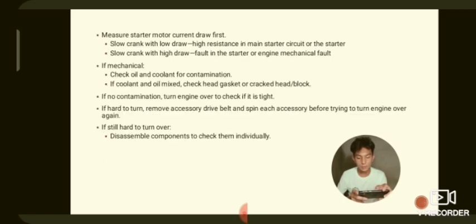Measure the starter motor current draw first. Slow crank with low draw: high resistance in the main starter circuit or the starter. Slow crank with high draw: fault in the starter or an engine mechanical fault. If mechanical, check oil and coolant for contamination. If coolant and oil mix, check the head gasket and or cylinder head block.